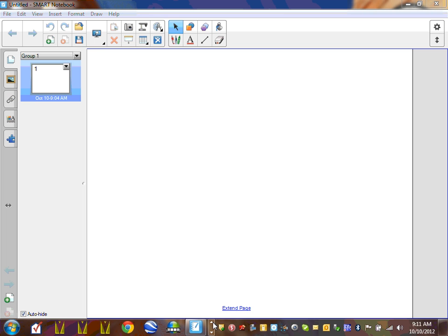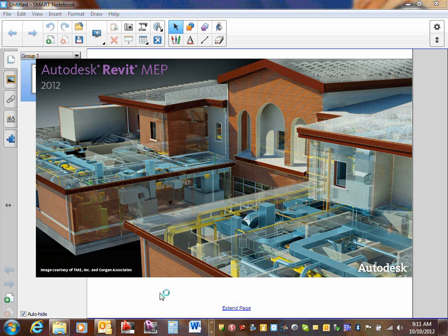So my exposure to one lines is with SKM Power Tools for short circuit calcs. You basically build the riser, except you build it in a one line form, and that's how you get your short circuit calcs. PowerTools is just another tool for you to learn, another thing to put on your resume, because a lot of places are looking for PTW experience. I saw an engineering firm about a month ago that was looking for a guy to pretty much run PTW specifically.